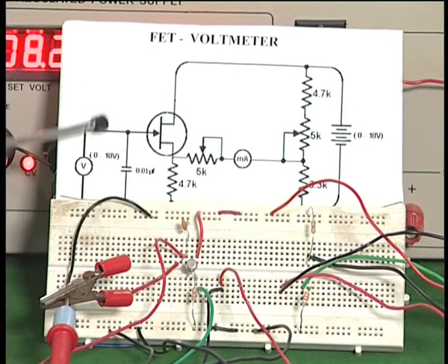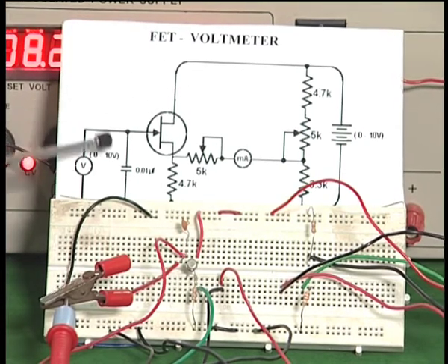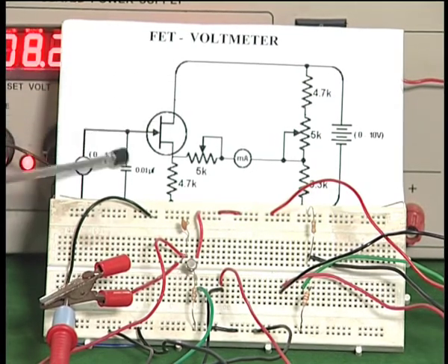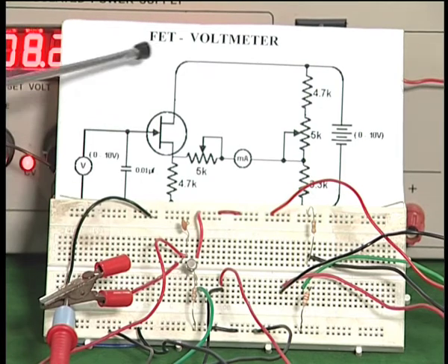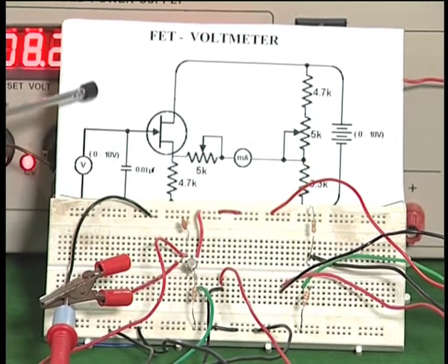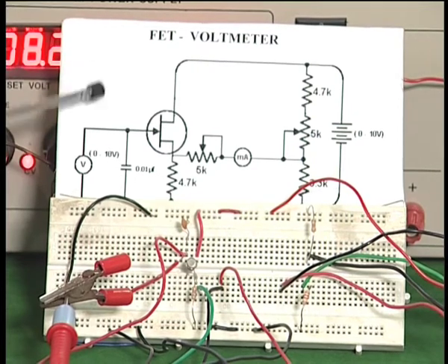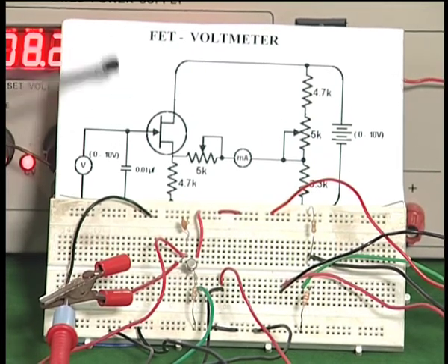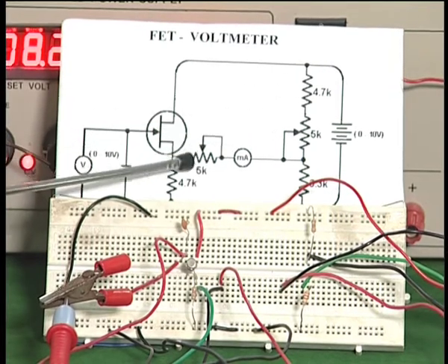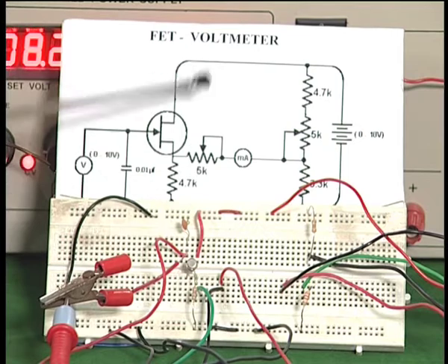So that is how I get a multimeter in principle. Multiple voltages can be selected and then the whole voltmeter can be designed. This will be a very interesting exercise to try to make this work for 0 to 10 volts, 0 to 100 volts and 0 to 1 volt for full scale deflection. You can adjust the resistors in the bridge and achieve this very easily.